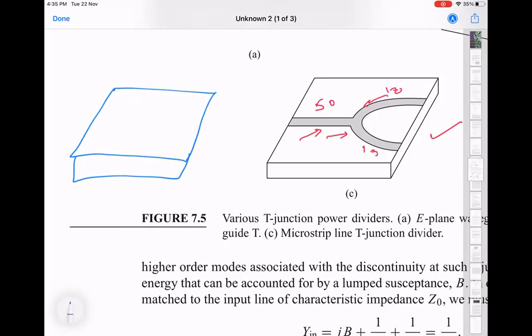The reason you have to do this is that in practice, if you're going to use this as a device, you're going to have connectors, right? So there's going to be some connector here, which is going to launch from coax onto, let's say, a microstrip. So this is going to be a 50 ohm microstrip line. So far, all that has happened is that there could be a long coaxial cable here coming here. That's also 50 ohms. This connector is 50 ohms. This microstrip is 50 ohms. So everything is just one big long transmission line in the ideal case.